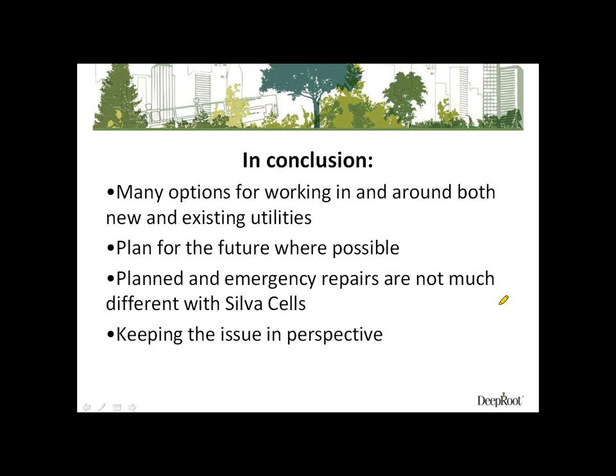As far as can they be empty, we haven't had a project like that. As far as from a structural capacity, the soil inside is not part of the calculations. So in other words, the Silva Cell, when you do the testing and the load testing and all that, they're done empty. And our test information does not include soil inside. That said, when you start not putting anything in there and you start putting soil around the outside, you get into some other lateral loading issues because there isn't that backing or mass when you're compacting.